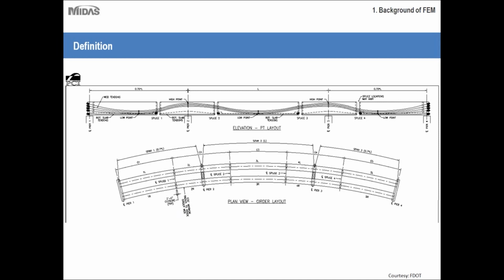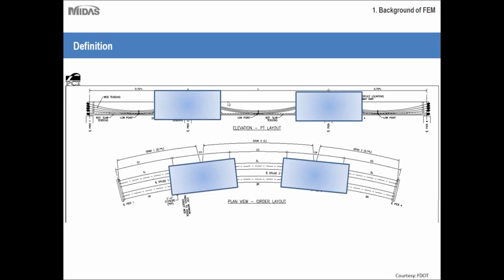So this is somewhat in line with the accelerated bridge construction practices, where you can cast these segments along the curvature, lift them up, and put them here in the zone where it is supported over the piers. In these zones you have to apply the lid slab on top to cover the U-girder opening and provide enough stiffness to the section to avoid any kind of torsion in the segment and give it its stability. Because after this stage we will be doing the post tensioning and applying the deck slab on top of it.